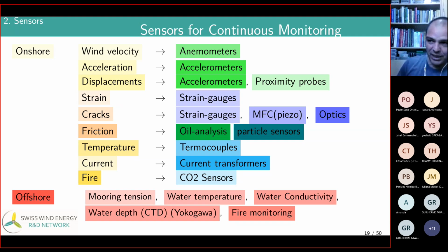The first mode of a blade is half a hertz, and on a gearbox, the largest mode that we need to measure on a blade will be less than 20 hertz. So the first 3 or 4 bending modes. On a gearbox, we might need to measure 10K hertz. That's a big difference. Same sensors, different measuring ranges.